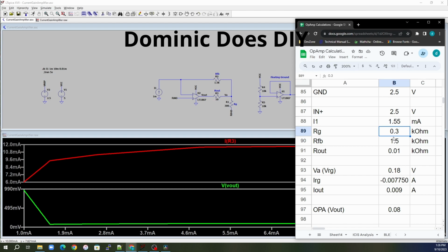So now the question is, what can I do to get to a higher current, right? How far can I extend this 1.55, or what can I tweak? Let's say I wanted to go up to 4 milliamps as an input current and be able to output 24 milliamps from this op amp and gain amplifier. Right now, if I just try to crank 4 milliamps, obviously I'm going to negative 3 volts, so this isn't going to work. Then what can I do to manipulate it?